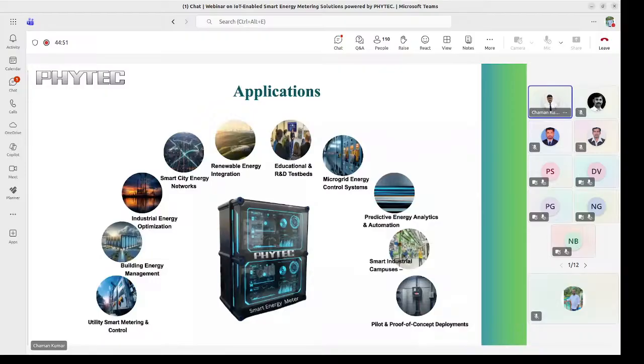Now for the load side, if the active power is greater than 400 watts. Right now for the practical demo I put the power limit at 400 watt. If the active power is greater than 400 watt, then it automatically disconnects. Let me connect again so that I can show that also. Now load is connected. Now if I send the active power greater than 400 watt, it will disconnect. So now see, I am setting the power greater than 400 watt, load is disconnected. This is how I am reading from the optical meter reader.